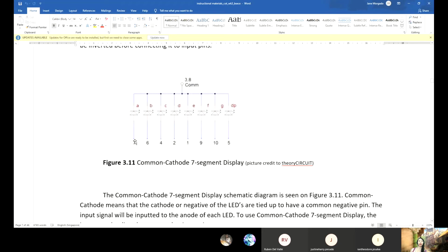So you have your design already, output A. You supply it here directly to the 7. Common cathode lets you directly connect your logic circuit design to the pin. Let's say you have logic circuit design A, that was your assignment yesterday. The output of which would be connected here in pin 7.